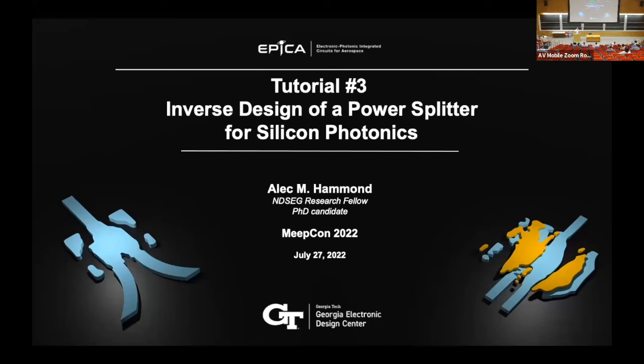Just want to make sure I got that. In theory, it shouldn't, right? But there is a slight difference in implementation between the two based on the DFT convergence. When you're only doing a single frequency point, you are only looking at the convergence of that one wavelength point. If you do multiple frequency points, you have to wait for the others to converge too. It could be that the other wavelength points force you to run the simulation slightly longer, or it could be that the adjoint sources that we created based on this fit, which I'll talk about tomorrow, don't have the same kind of accuracy as for a single frequency. So you will see some slight differences between the gradients there. Obviously, the structures will be completely different, but the gradients should be pretty close to each other.